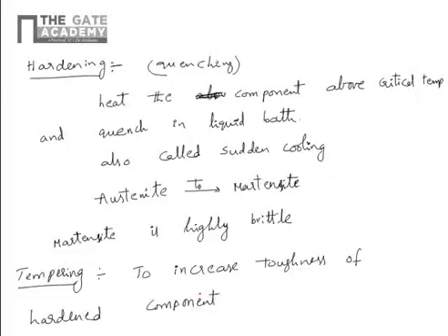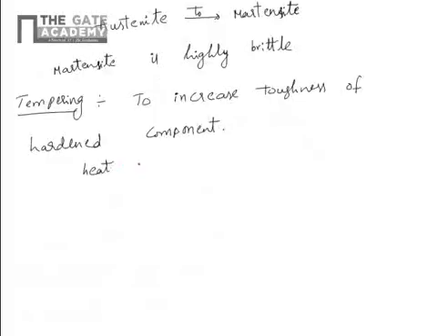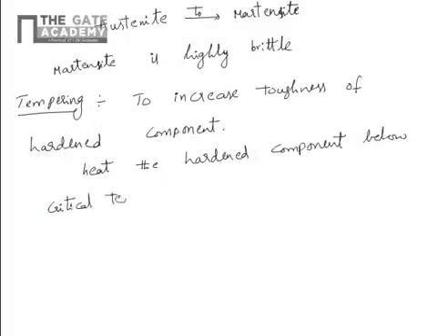So to increase the toughness of the hardened component, what we do is heat the hardened component below critical temperature and cool in open air.